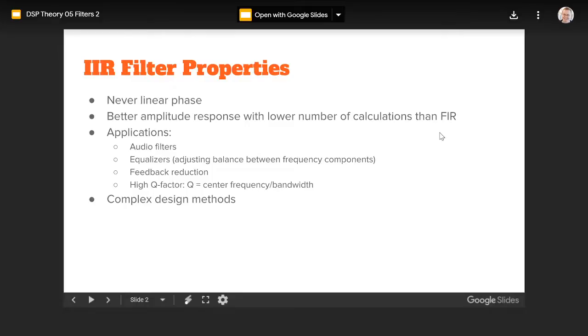I'm not going into details of how to prove it, but that's the case. That's how you get the amplitude response, but then to flatten it you put some attenuation and attenuate this so that it falls like that. Okay, so that's the way to flatten the passband attenuation in the case of FIR.